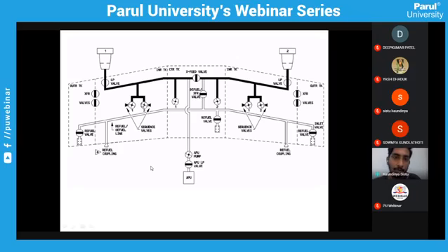Again, it will go to the booster pumps, which is a dead end, because booster pumps take the fuel and pump it inside. It can't allow the other way. It's only one way, so it's a dead end. It will go to here. Again, if you open the LP valve of the number one engine, it goes to the number one engine and the engine just starts.